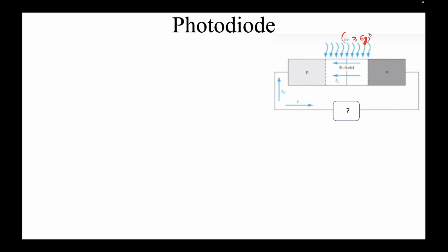But you can detect too much. For instance, silicon band gap is 1.1 eV. Corresponding to that, the wavelength that comes out is around 1.1 micrometers. So any wavelength 1.1 micrometers or lower you can detect. So for instance, you can detect visible with a silicon based photodetector very comfortably, because our visible wavelength is 0.4 microns to 0.7 micrometers, right? But you can also detect UV, which is below, let's say 350 or 300 nanometers. So the silicon photodetector will detect a large number of photons of varying frequencies, right?